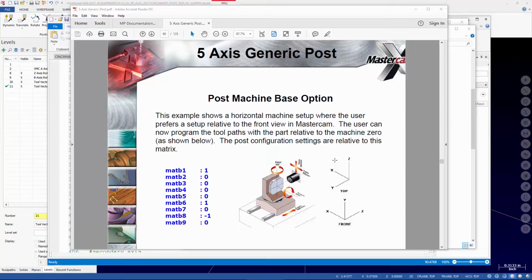Then we have to figure out either a toolpath that will just let us do one rotary, or we have to be able to break up the motion in the post, or in some cases, maybe if that's not desired, we should at least warn you if there is simultaneous rotation in both axes. So be happy to take a look at that on an application side, let's get a little more info from you.